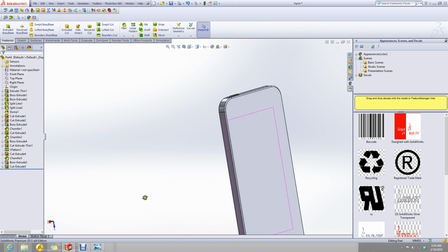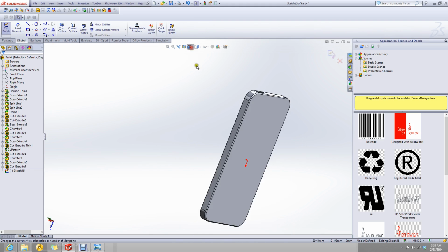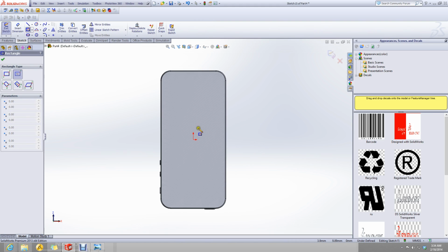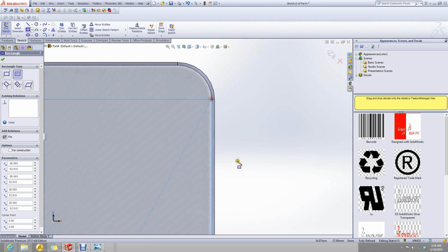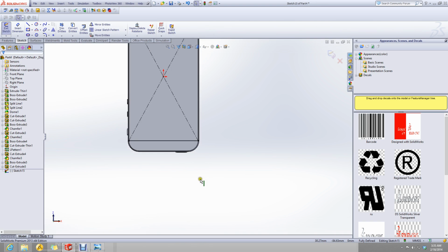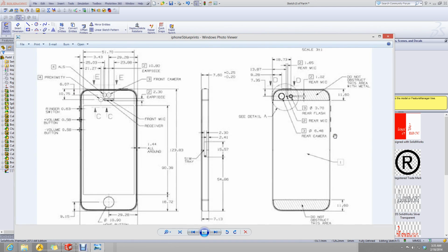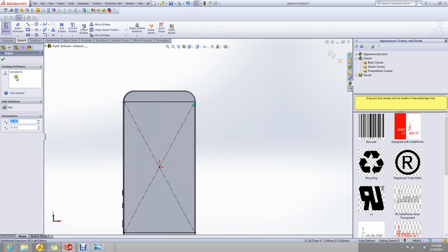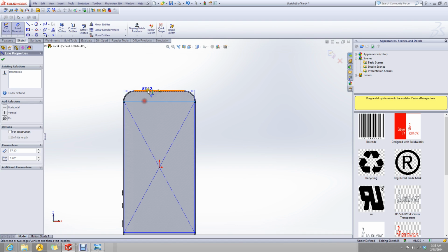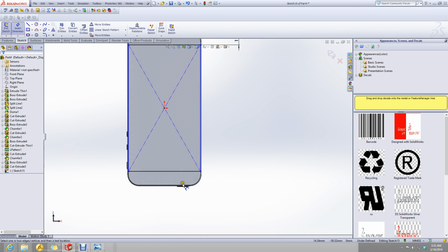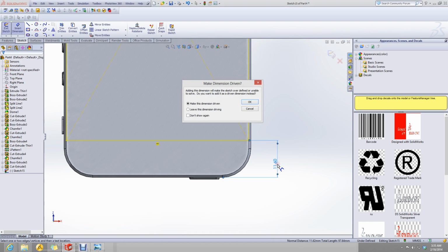Okay, now let's come towards the back. At the back we have to separate the face. We create a corner rectangle, center rectangle, sorry, like this. Okay. The distance of this is 11.6 from the top and 11.6 from the bottom. So instead of making this coincident, 11.6 from the top, it automatically becomes 11.6 from the bottom, like this.